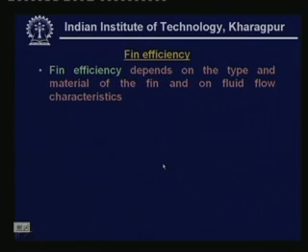So, whenever fluorocarbons are used in water cooled condensers, the tubes on the refrigerant side are made integrally finned, so that you can enhance the heat transfer on the refrigerant side. In such a case, you have to consider the fin effectiveness and the fin area on the refrigerant side. Now let us look at fin efficiency. In finned heat exchangers we have to find the fin efficiency.